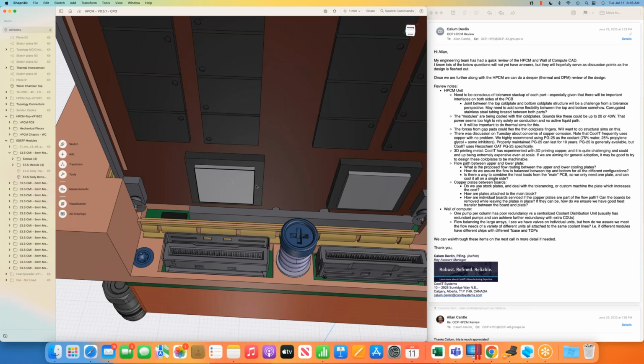And these are ones where you'd want to maybe, and they're probably slightly higher profile, mate with grease or as efficient a gap pad or thin a gap pad as possible. Whereas these lower power devices, you just have gap pad, just like you see in the modules today. When we took a Micron CXL.mem module apart at the MEMCon, Micron kindly did that, we saw gap pad all over the place. So absolutely, in that sense, you're absolutely right, Callum.